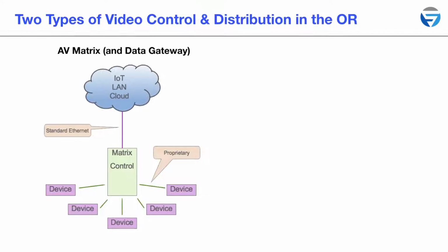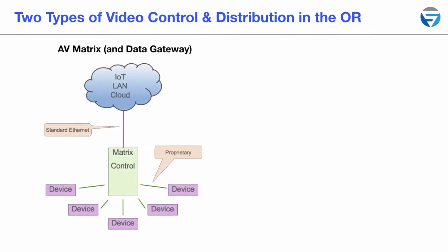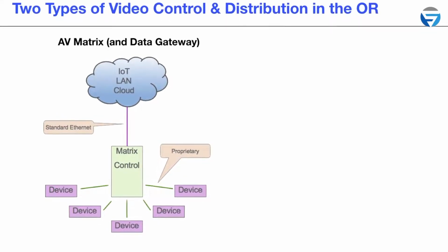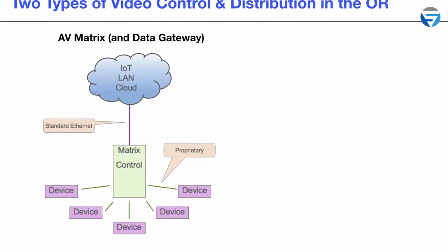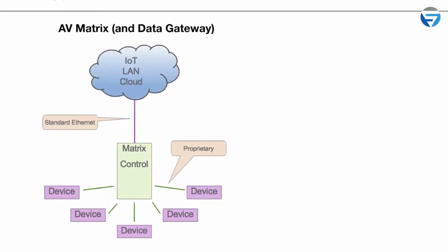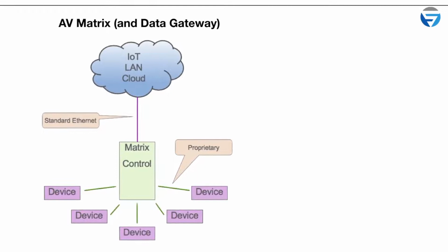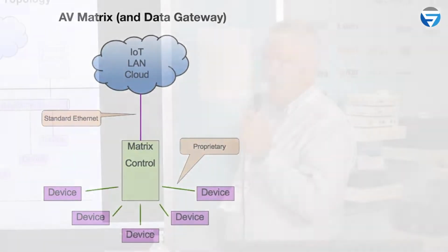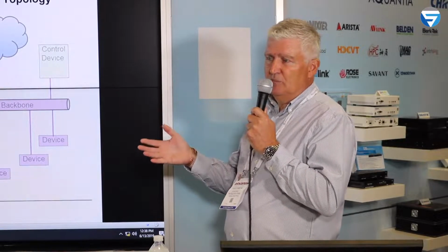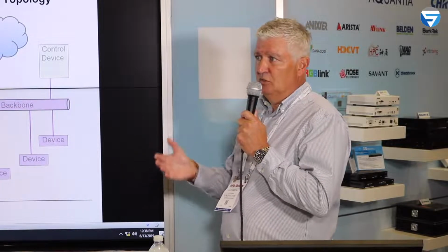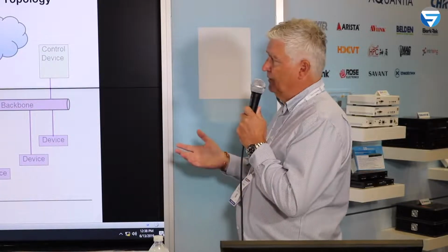So we have Karl Storz, I think, went up to 32 by 32 inputs and outputs. I think Stryker were 18 by 18 on a video matrix. So they're all around there with a professional video matrix, 12G SDI, HDMI, and now another option would be HDBaseT to make use of Cat5 cable, for example. But these are all proprietary, closed systems, just for the purpose of distributing video. HDBaseT, of course, has the 5-play, which will allow some internet, some IP connectivity.